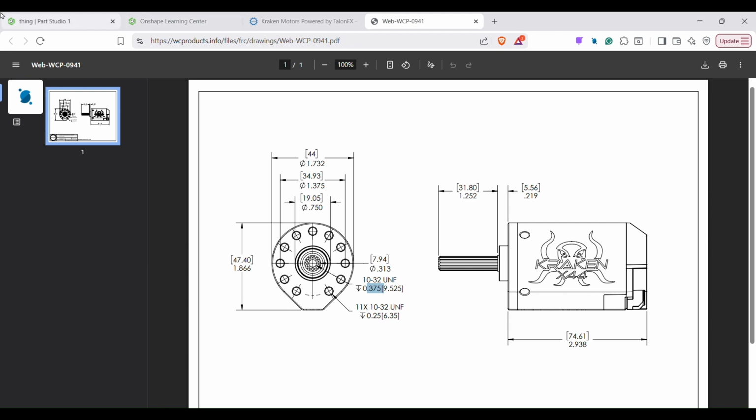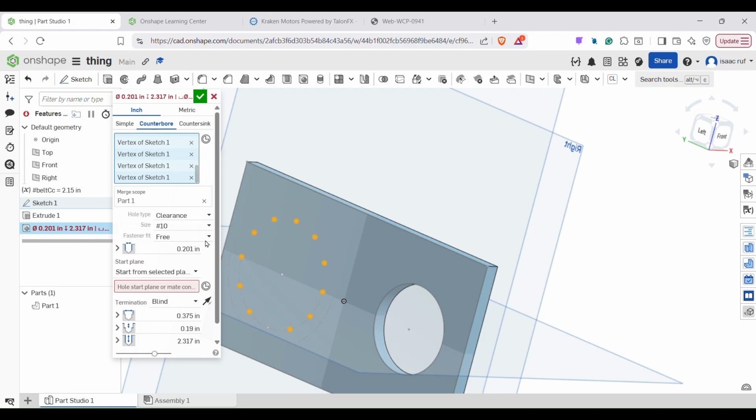We are going to use a close fit option. Right now it says free. We want a close fit. You could do close or close ASME. ASME is just a standard. You can do either of these. So actually, if you're going to do close ASME, you should do normal fit. And that will make it what it wants. 2.21. That's the dimension for the number 10 bolt.